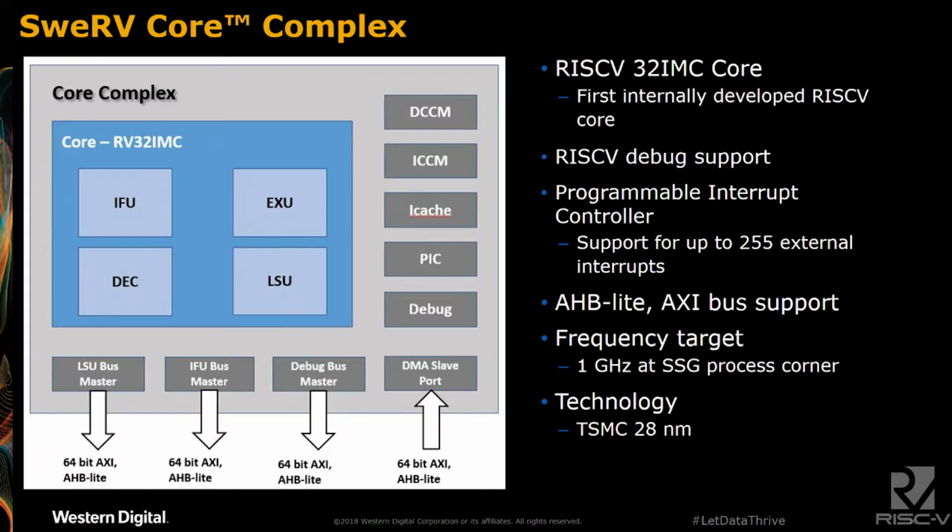With compression, typically we see about 40 to 50% compression. That's typically what you find in the RISC-V reader. We see that same sort of compression. We only have 4 units on this core. It's a very simple, basic core. First, an instruction fetch unit. We fetch up to 16 bytes per cycle from either an ICCM, closely coupled memory, or an instruction cache. We have branch prediction in the IFU. We do the alignment of the instructions in the IFU.